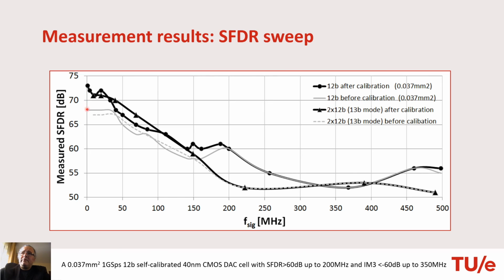This performance is kept up to 50 megahertz, and beyond that dynamic errors start to kick in, so the performance decreases, and it again stabilizes to a level of around 50 dB, 55 dB at high frequencies.